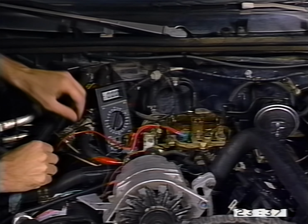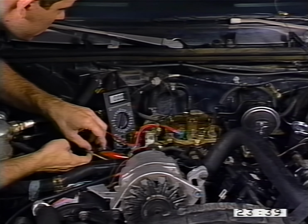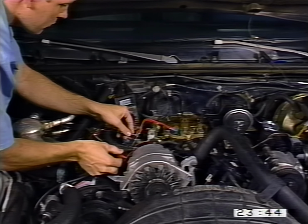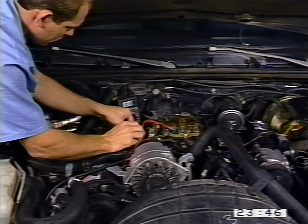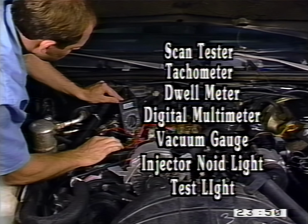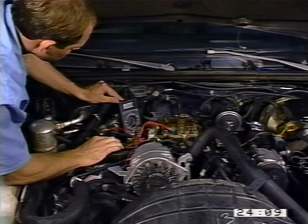Now, let's review how to diagnose the C3 system. Computerized engine control systems are easily diagnosed using onboard diagnostics and with the use of a selection of tools including a scan tester, a tachometer, a dwell meter, a digital multimeter with a minimum 10 megohm input impedance, a vacuum gauge, and fuel injector test light for both throttle body injection and port fuel injection. A test light rather than a voltmeter must be used when called for by the diagnostic chart.